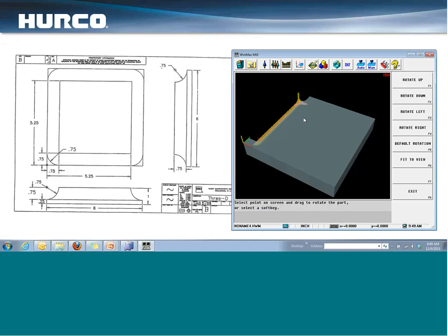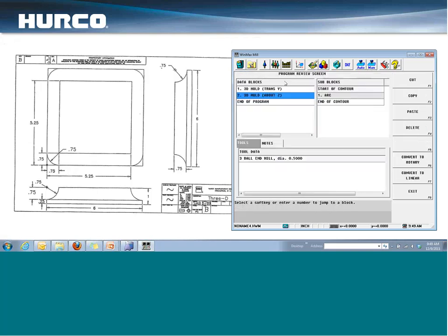So one of the limitations of 3D mold is that if we want anything along the X-axis, we're then going to have to apply our standard patterns in order to get that geometry where we want it. So in this case here, I'm going to insert a block before both of these data blocks, and we're just going to rotate both of these blocks around the center point of this part to get it on all 4 sides.